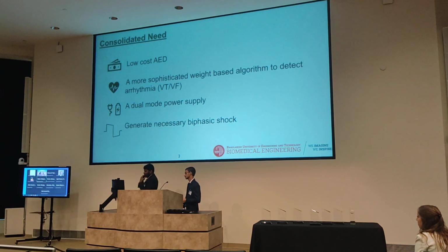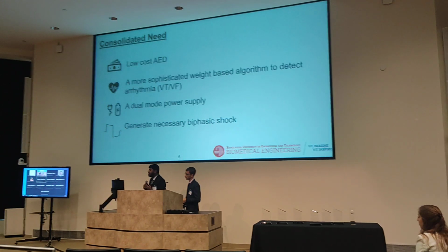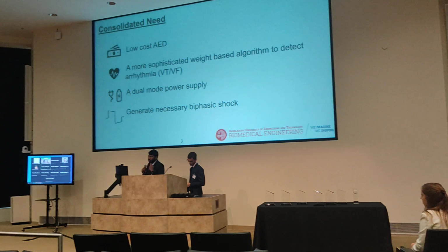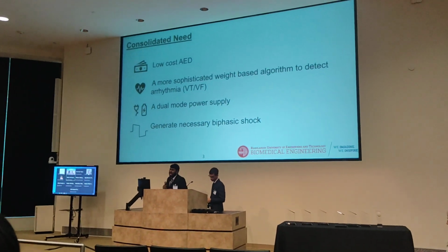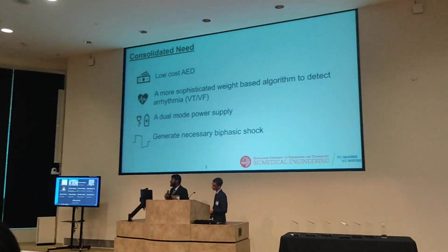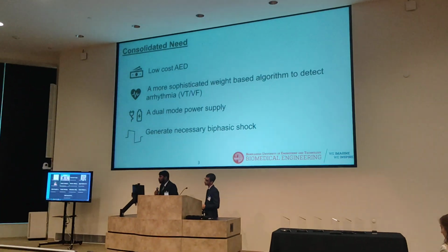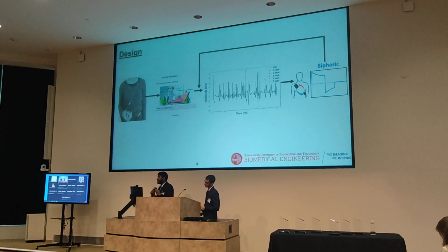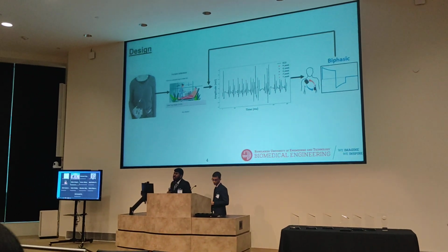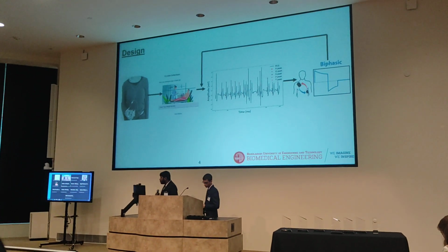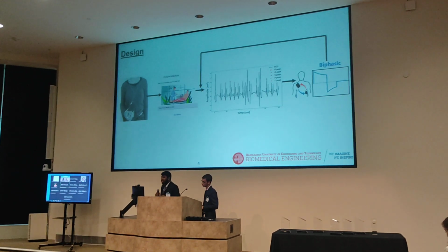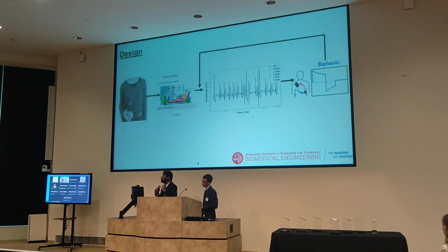And since lower-income countries have a power problem, we need to make it connect with the supply line and a DC line, and we need to produce the necessary biphasic shock. So we have designed an AED, and we have innovated a weight-based algorithm, which can detect lethal arrhythmia and will provide the necessary shock, with respect to the weight, if the arrhythmia is detected.